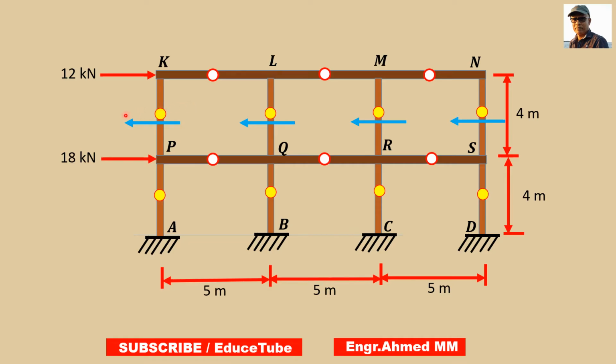Let's say the shear at the exterior column is V. Then for the inside column, of course, it will be 2V. And for this floor, it will follow the same rule: here V1, here it will be 2V1. This is the third assumption.